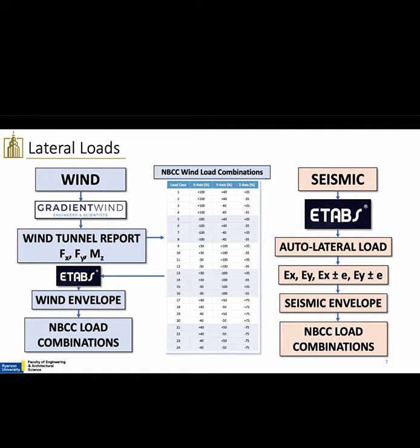For the lateral loads, we had a wind report provided to us from Gradient Wind, and we imported those loads into ETABS with these 24 different NBCC load combinations. We also used the auto lateral load for ETABS to produce the seismic envelope with the NBCC load combinations.